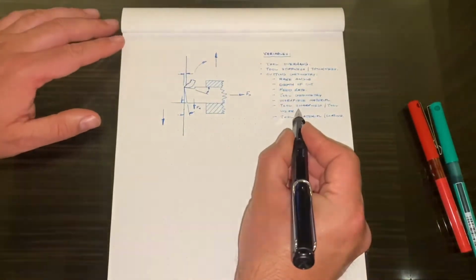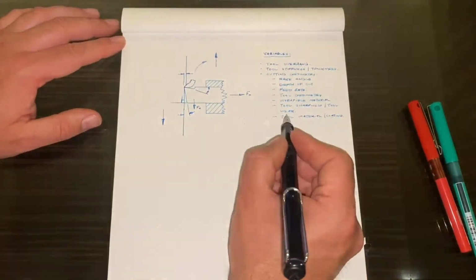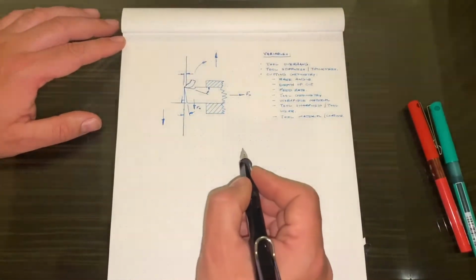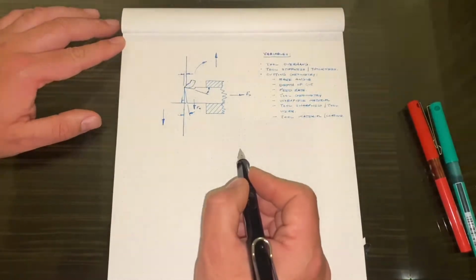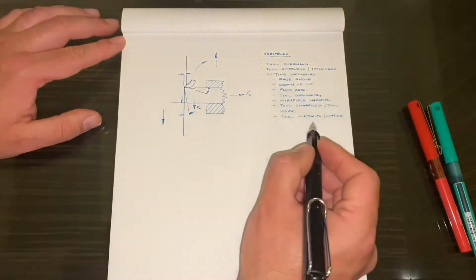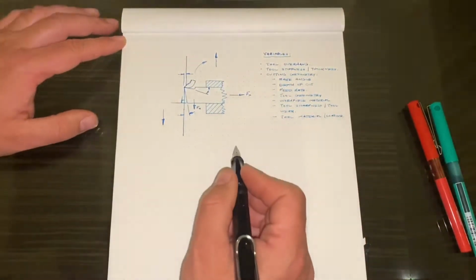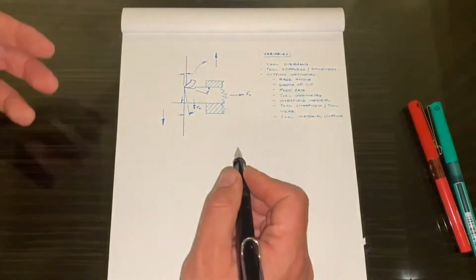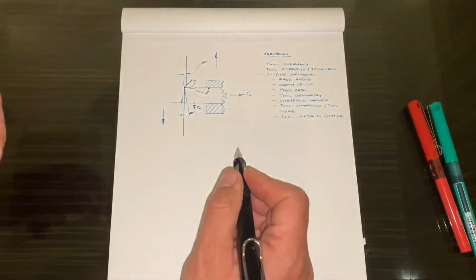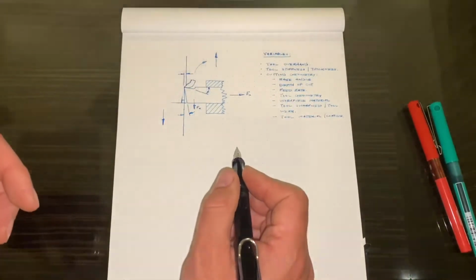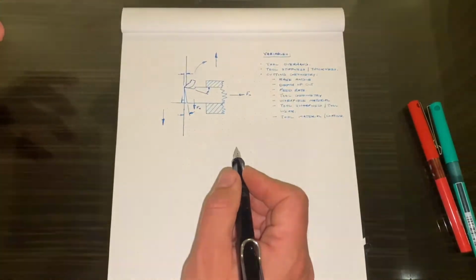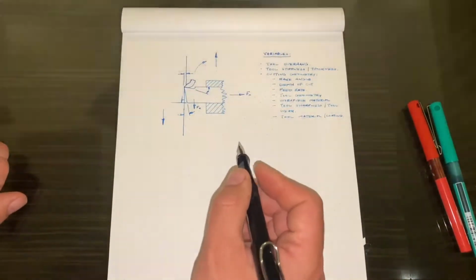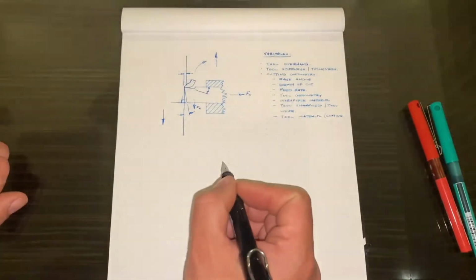Tool sharpness or tool wear, a tool that's lost its edge will require higher force to do the equivalent work of a sharp tool. And tool material and tool coating, so some tools have titanium nitride coatings, which are a low friction coating. That can be very helpful to reduce tool wear because friction is reduced. But tool geometry is the point that I'm going to come back to now.